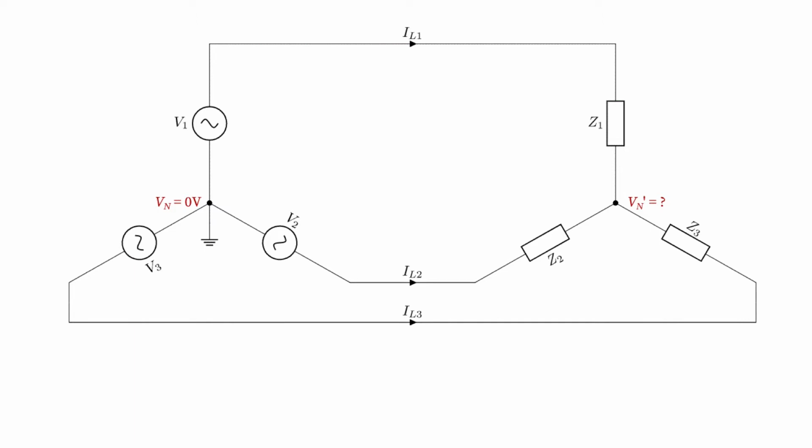First of all, if the network is perfectly balanced, and we've talked about balanced networks in a previous video, we know that the current at the neutral point will be 0. And given Ohm's law, V equals I times R, it means that the voltage at this neutral point is also going to be 0. So actually it doesn't make any difference. Assuming that our network is perfectly balanced, then there's no effect of removing this neutral conductor.